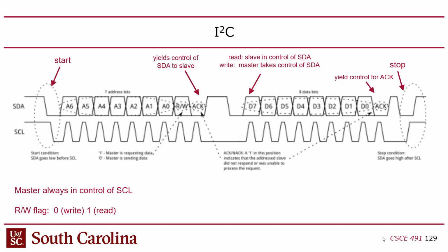Notice here that when you start this up, of course, both signals are high because that's the default for open drain, but notice that the data drops first, right? It happens to be dropping when the clock is high, though, right? But that never happens when you're sending data. You don't change the data when the clock is high because it's level sensitive.